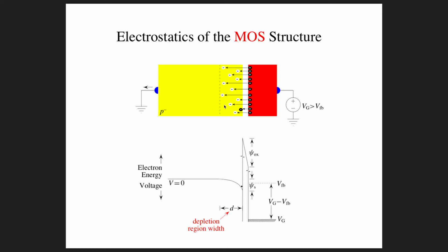The hole that we pushed away here is an extra hole that gets collected as a little bit of current flowing out of the bulk terminal here. And so we have a situation where we have this little low spot in the energy landscape where an electron can sit in that little notch. Okay, so if there's an electron that comes in here, it's going to want to sit up in that little notch, that little low spot of energy.